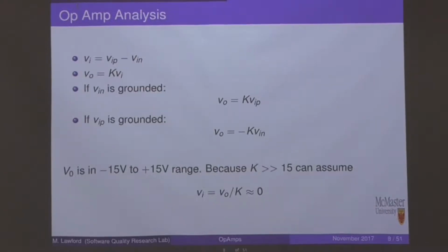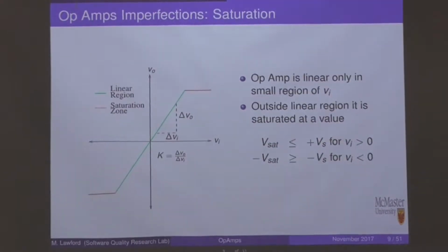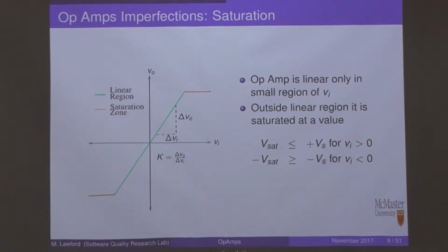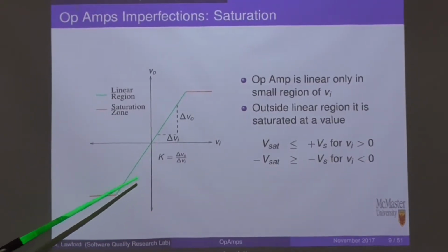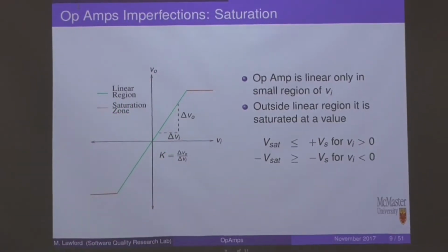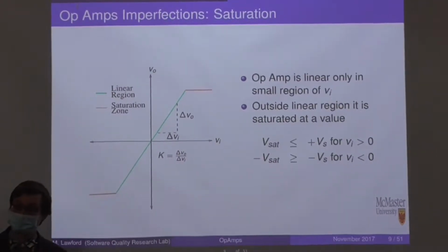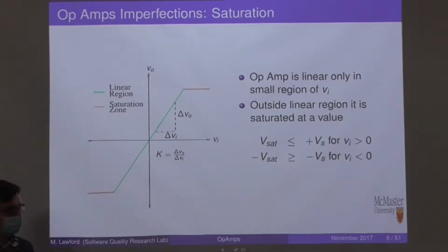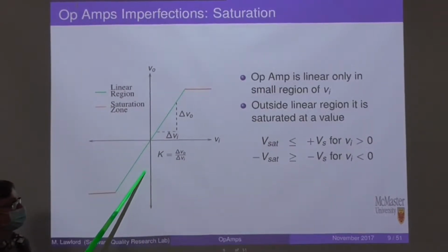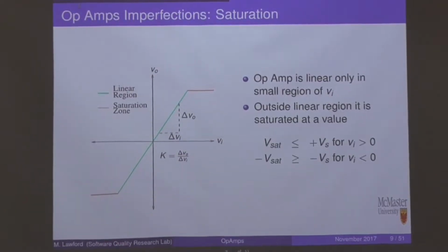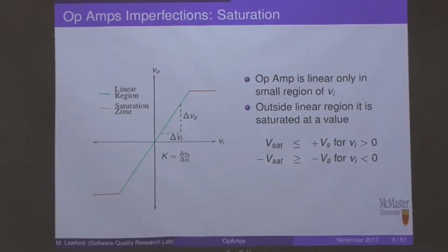So, one thing that perhaps we should note before we go on, reiterate: the gain on an operational amplifier, if you use it in open loop mode, so if you don't connect any feedback into the operational amplifier, is quite large. It can be in the 10 to the 6 to 10 to the 9 range, which is just ridiculously huge.